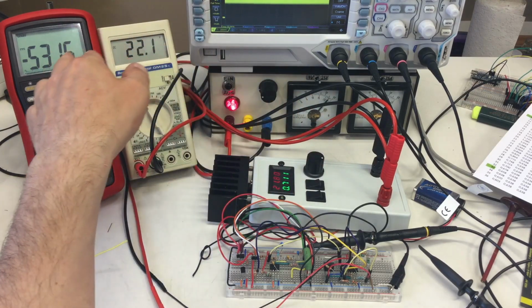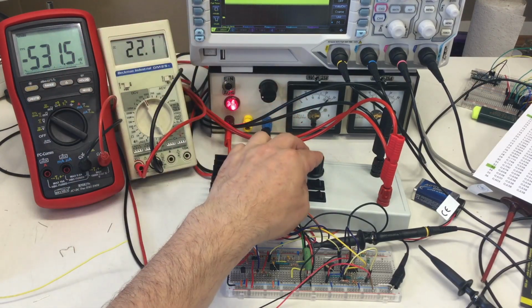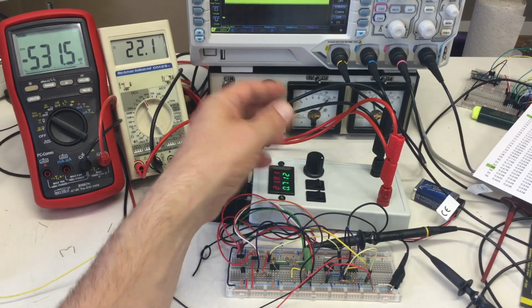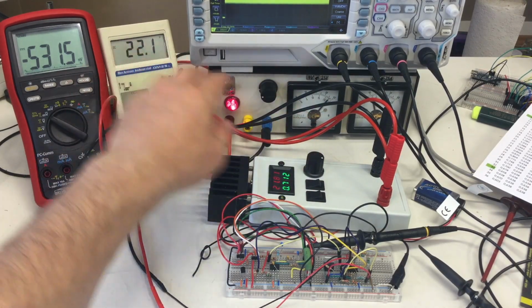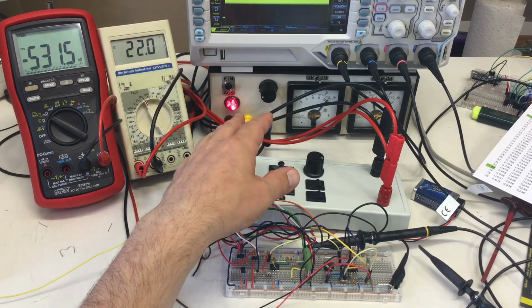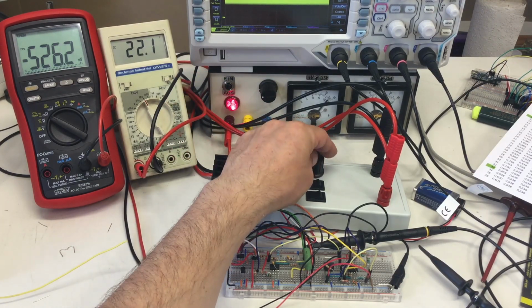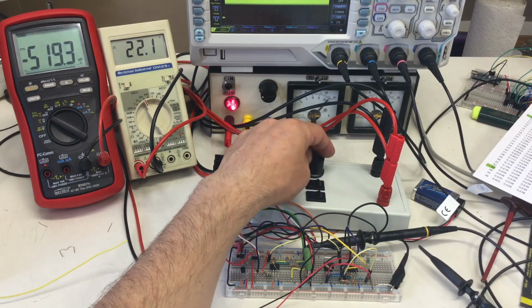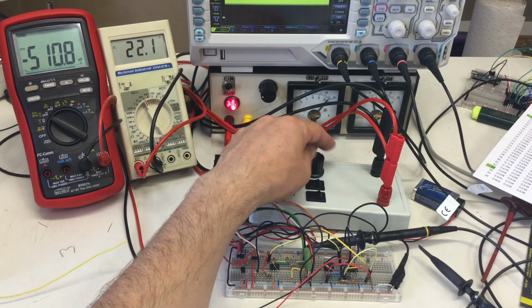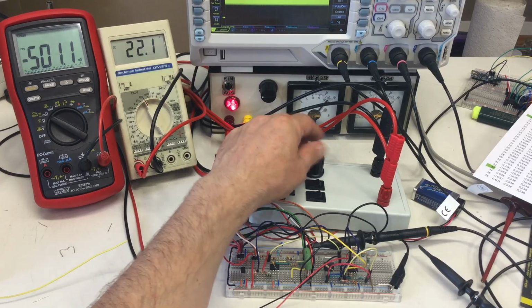It might go up to 600 millivolts under extreme conditions, so really at input voltage 35 volts. And it's a diode, the voltage drop changes according to the current going through it. That's a drawback of that very simple circuit.